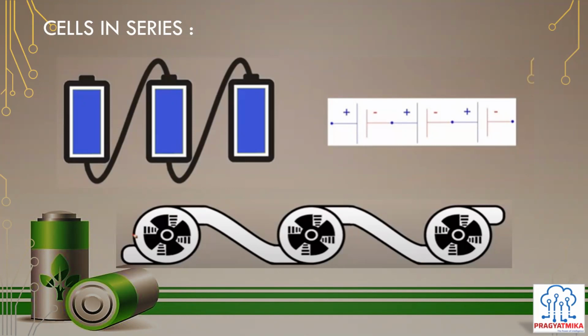The base of your electrical design starts with the cell and battery pack calculations, which also give the capacity estimations for the battery pack for any application. As per the capacity estimations, you will require a number of cells to be connected in series and parallel from the electrical rules, so that you can get a particular voltage or a particular capacity from the pack, because one cell has very limited capabilities in terms of both voltage and capacity. So it starts with the cells in series, and the series combination gives you the accumulation of the voltage.